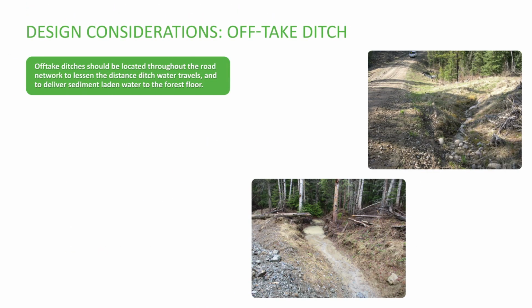Here are some design considerations for offtakes. Offtake ditches should be located throughout the road network to lessen the distance ditch water travels and to deliver sediment-laden water to the forest floor. Ditches should not drain directly into a stream.